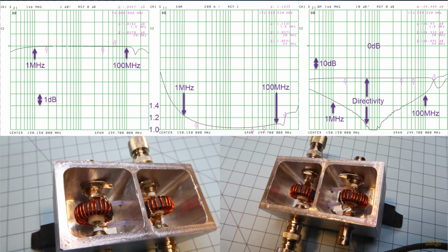So this circuit could handle pretty easily 100 watts at about a 3-to-1 SWR without any trouble. It certainly won't make it to a kilowatt. I put 600 watts into it for about 5 seconds, and it got noticeably hot, to the point where when I put my hand over the top of this enclosure, I could feel the warmth coming up. So it can't handle high power. But nevertheless, this circuit is a pretty good circuit to use on the output of a 100-watt transceiver.